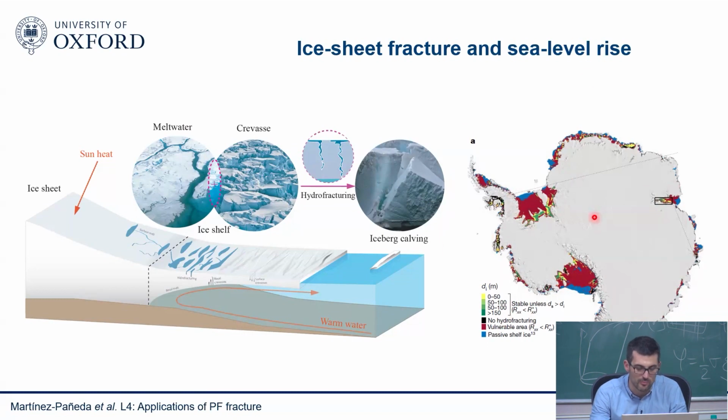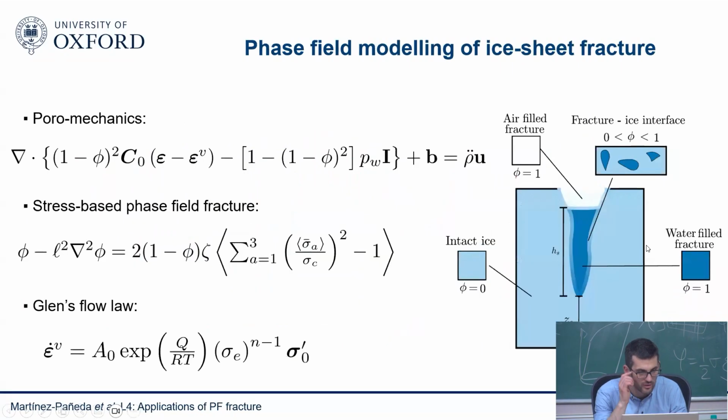And linear elastic fracture mechanics is okay. It's not about approximation. But here we have creep. So that is a history-dependent problem. No longer should we apply superposition and so on. And we have other phenomena. So we try to go a bit beyond what these people have done. But this is fine. This is good stuff. So what we try to do is to develop a phase field model for ice sheet fracture. It has multiple ingredients, some of which differ from what you've seen before. So maybe I'm going to start from the bottom first.